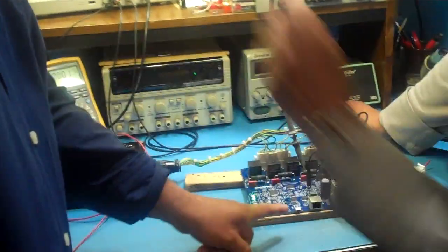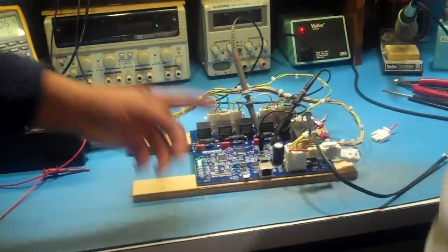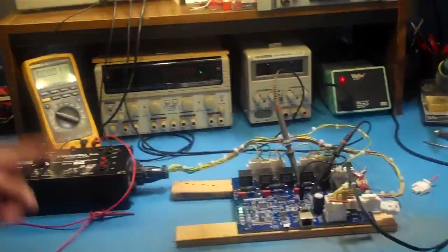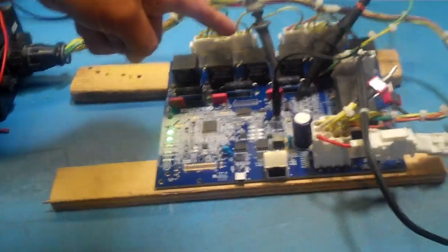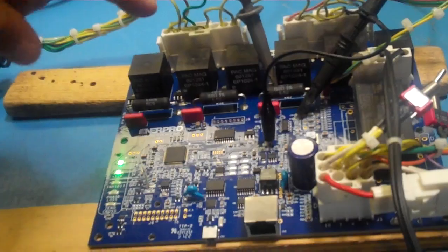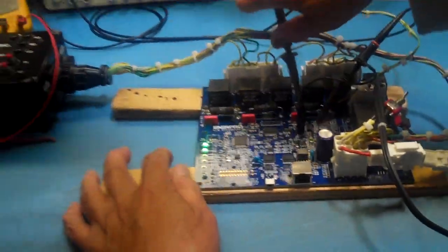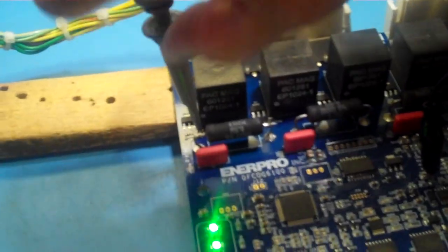So again, we're not using the RJ45. It's actually J13. The board has to be inhibited. And then what Tony does is he's got test point 4, the phase reference. And the other one, can you just remove that, Tony? You can either use 4 or 1. It doesn't matter.